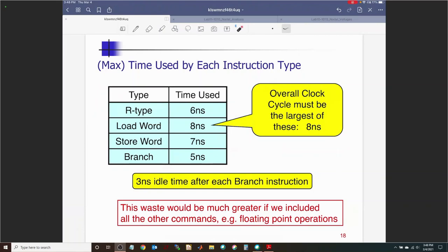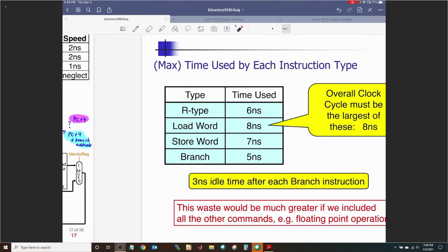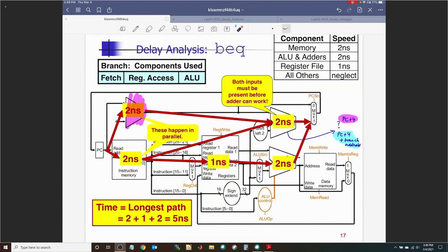This matters because the next time we meet, we will start talking about pipelining. Pipelining is a very elegant concept in which you are trying to make sure that almost all your resources are being used all the time. What I mean by that is, you have an instruction fetch, register file here, memory here, ALU here. So there is a bunch of hardware, right? But if you are looking at only one instruction going through, then only one instruction uses this, and after it is done, the next instruction comes in. So what about using the fetch cycle for a different instruction once the first one is done, right? So that's leading into pipelining.